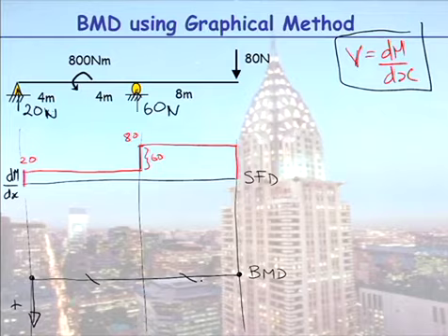So again, joining the dots, we know our bending moment is 0 at the cantilever end, and it has a slope of 80, so that means it's a linear line with a slope of 80. When I come and draw my other line now from the left support, because my slope is 20, I'll just automatically draw it less steep.